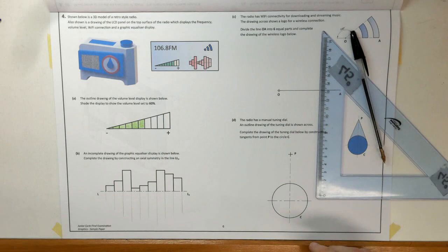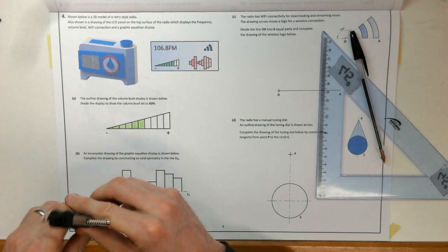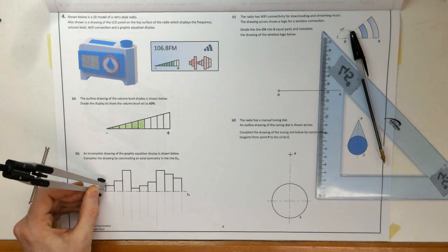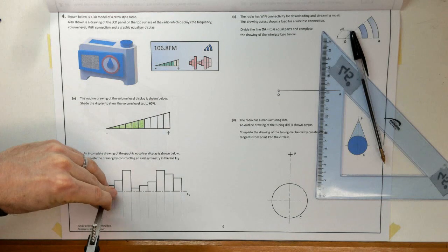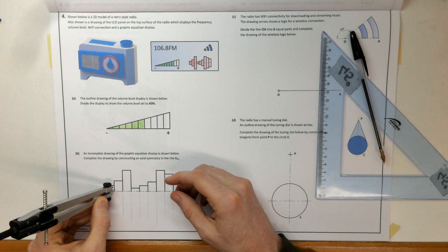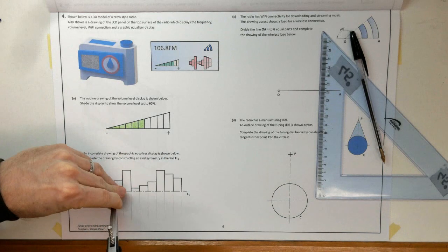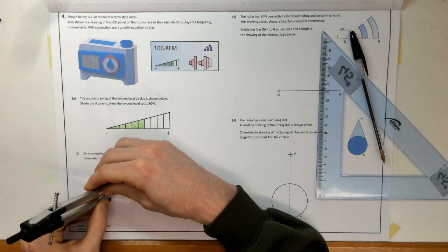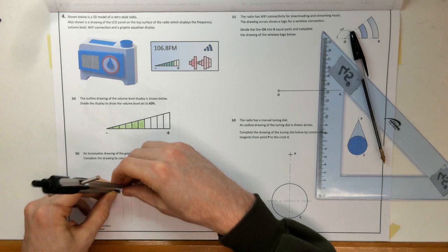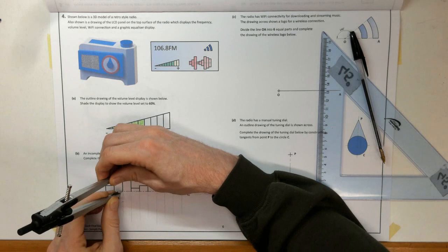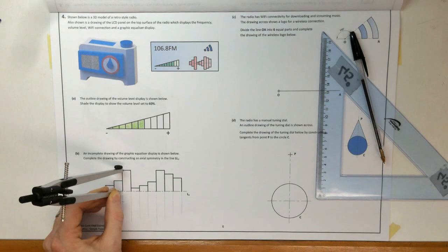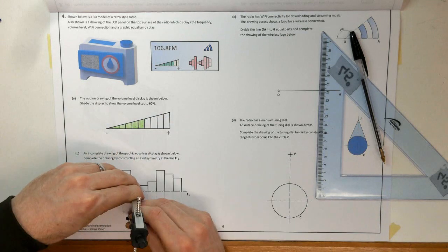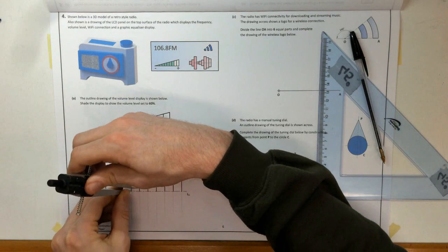Okay, and I'll get my compass now. So the distance, put my compass on the axis of symmetry, so line LL1. Get that distance from one side, transfer it to the other. Okay, it's going to be the same distance here for that point, and let's also find the next one. Bring it down. I have to find the end of that line, so bring it to the next one and down again. So just getting a bit repetitive here, but we'll just be patient with it. So that distance brought down onto the line projected through, and same again. And onto a very small one.